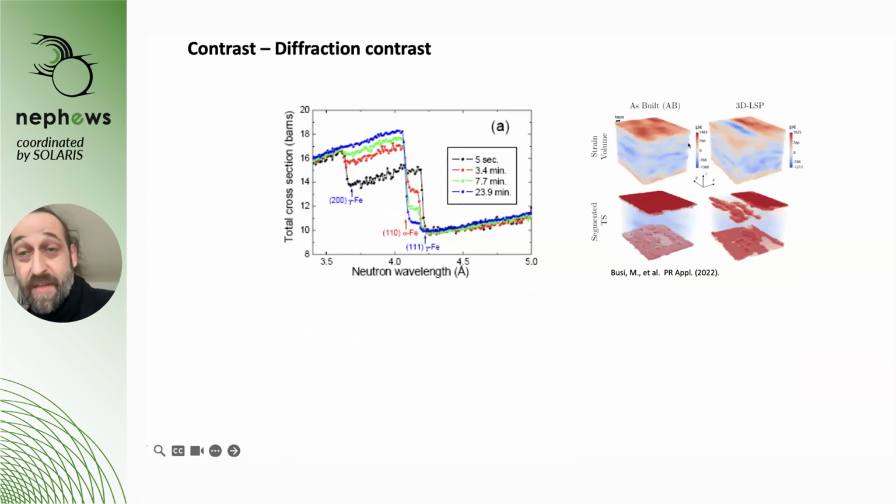And in this example, we have additive manufactured steel, and we can see how we have an increased tensile stress on the surface. And we try to counter this here in this example with laser shock peening, and we also do 3D laser shock peening. That means when we do additive manufacturing, we can do laser shock peening on intermediate layers, and then continue printing. And this way, we can basically design the stress field in these materials.